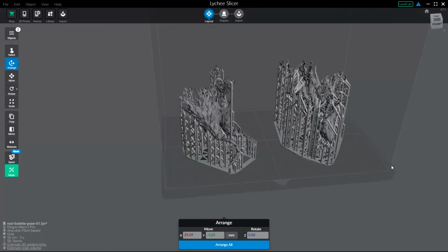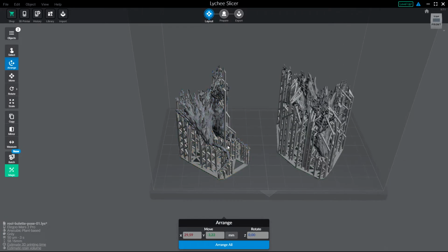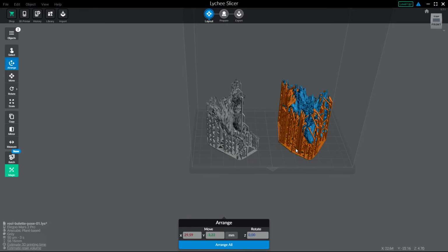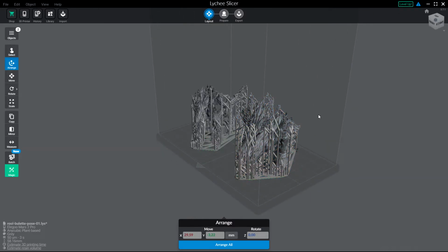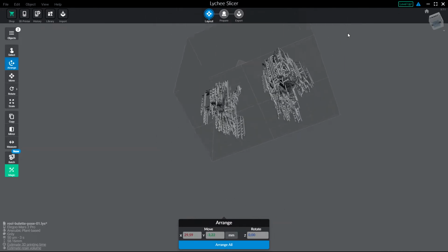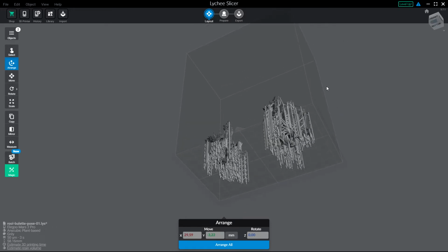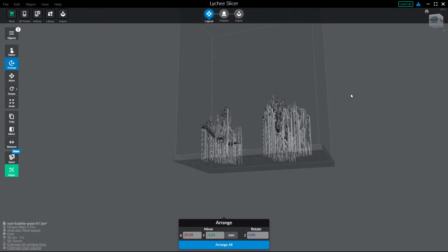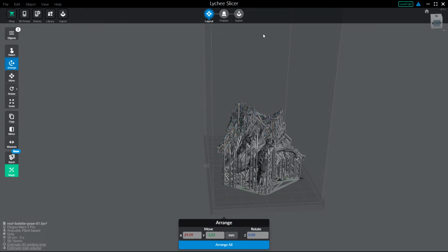You can fill your build plate up completely, and it doesn't matter for the print time, because it does one layer at a time, not one line at a time, not one pixel at a time, one layer at a time. Just the build height matters for printing time.